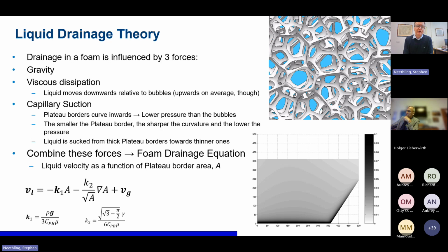So the motion of the liquid is critically important to both the overall entrainment, but also to the recovery of particles in the froth. And the way you should think about a flotation froth, or any other foam or froth for that matter, is really as a network of pipes. These are the plateau borders. Capillary suction means that you end up with comparatively thin lamellae or films between the bubbles, and most of your liquid is in these plateau borders.